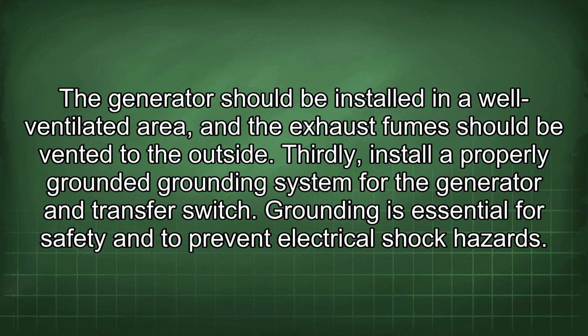The generator should be installed in a well-ventilated area, and the exhaust fumes should be vented to the outside. Thirdly, install a properly grounded grounding system for the generator and transfer switch. Grounding is essential for safety and to prevent electrical shock hazards.